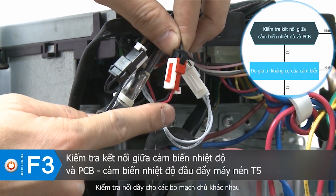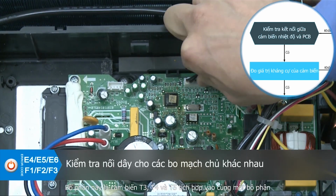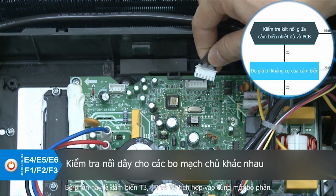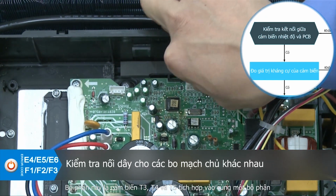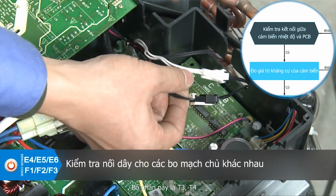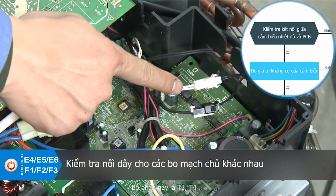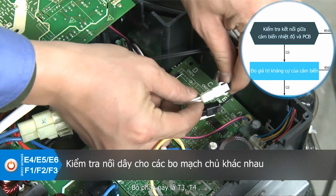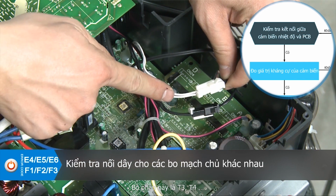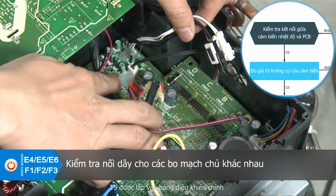Check the wiring of the sensors for different main boards. In this structure, T3, T4, T5 sensors are integrated onto a sub-board. In this structure, T3 and T4 are on the sub-board, and T5 is inserted in the main control board.